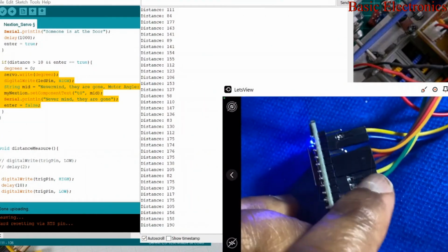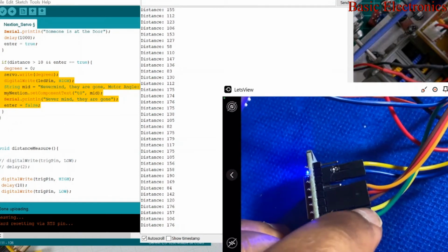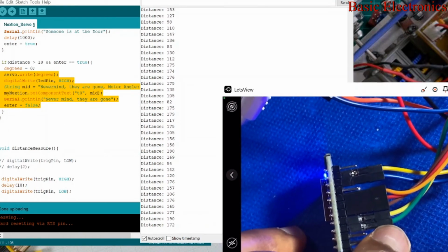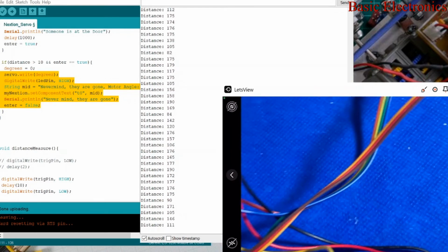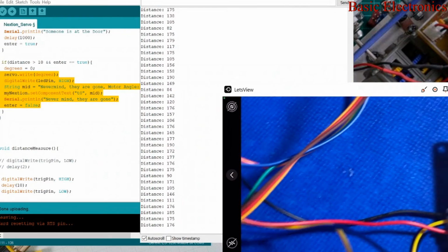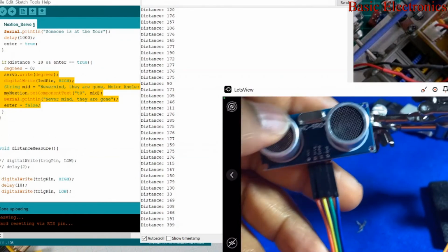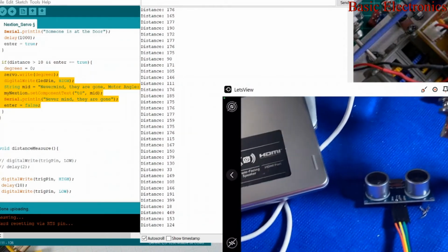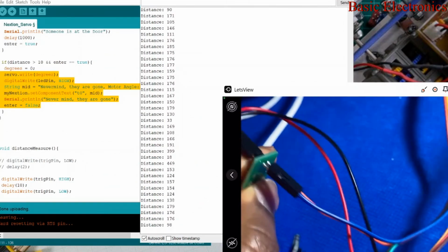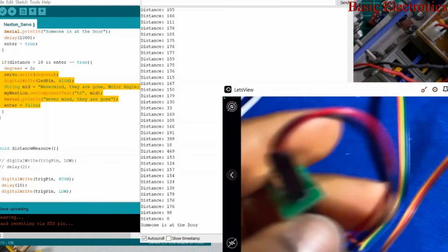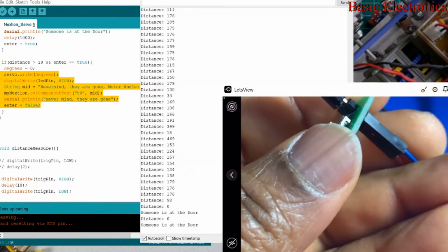We had the trigger pin and the echo pin added, so that's pins GPIO 14 and GPIO 12. We added those, and then obviously we need 5 volts for the ultrasonic sensor. To achieve that, we have this that came, I'm gonna unplug it now, but this piece came with the Nextion editor.